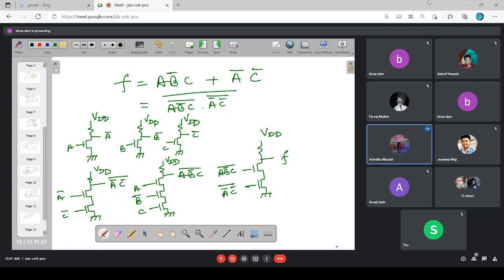Don't go for wiring the two terminals like this, as that will make the circuit clumsy. Just simply write the node voltage names, and it is implied that wherever the same name is written, these two terminals are connected. So there is no explicit requirement of wiring the two nodes, provided you have given the names properly. That's all.